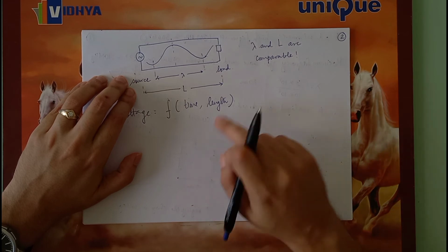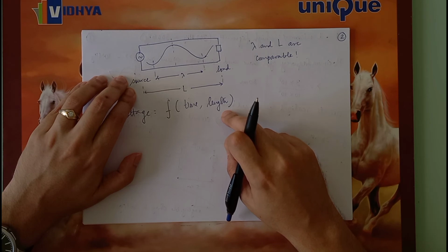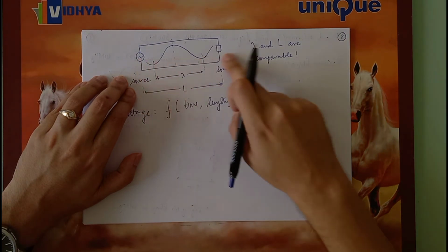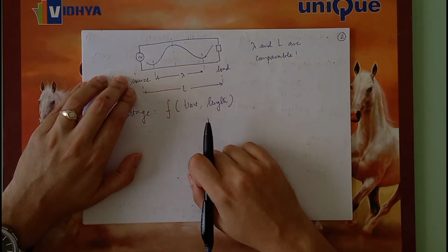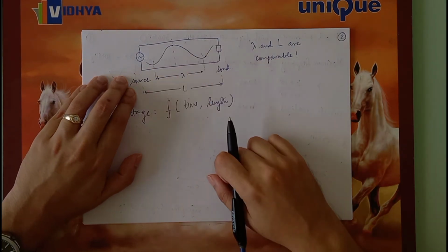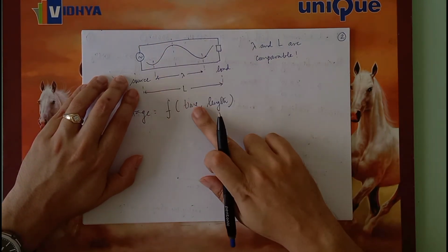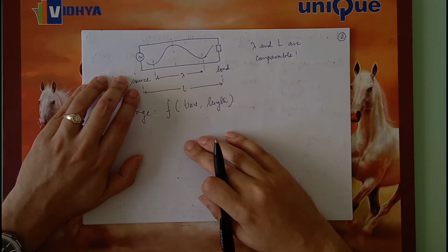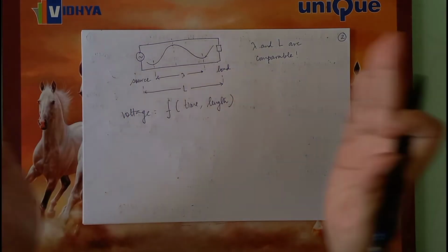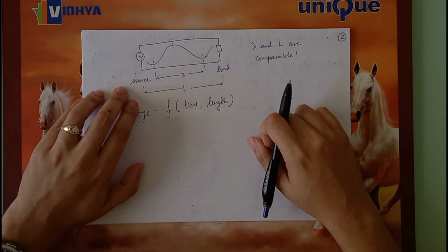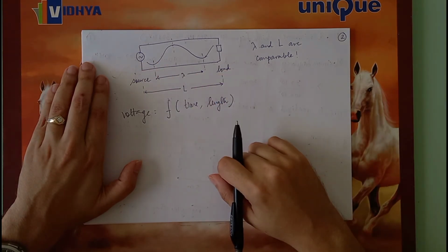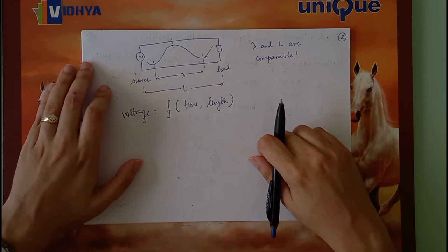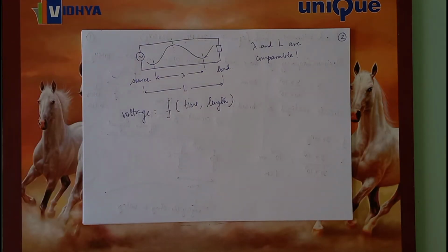Likewise, we are going to have some kind of a length distribution, or the voltage distribution on the line as a function of length, once we know what kind of function the voltage is with respect to time. So therefore, we can treat the time and length effects independently, although for a complete clear picture, they must be brought together. So this is the very basic difference between the circuits that you analyze or use in your basic courses versus an RF circuit.